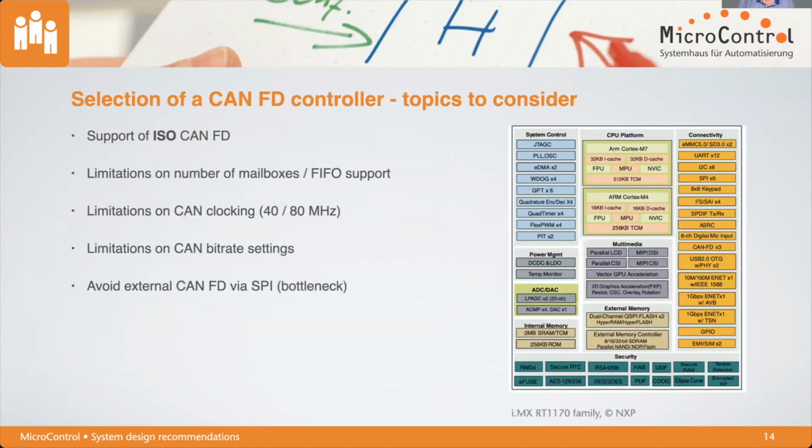And there are some more topics to consider. First of all, something which has not been mentioned here today: please make sure that the controller you select really supports ISO CAN-FD. There are still some devices in the world sold by silicon manufacturers which, as I remember, are described as a CAN-FD Bosch 1.0 standard and things like that.